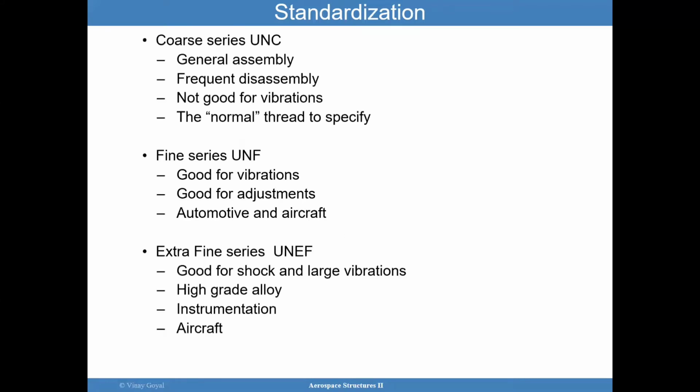We also have to discuss that the coarse series UNC provides the ability for general assembly and frequent disassembly, but it may not be very good for vibrations. And that was discussed just earlier, that the UNF series tends to be the better choice for fatigue-driven environments, such as those where the sources are vibrations or repetitive loading.